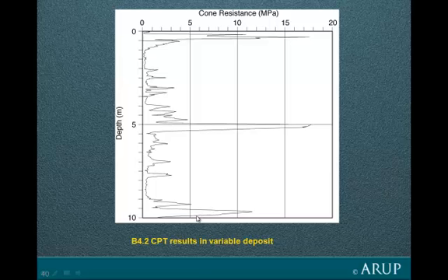Can I drive into it and be sure that it's then going to be the dominant stratum for the base? Or is it rather thin? Are we going to go back to some weaker material below? And this would affect the choice of characteristic strength for the base, and it might be very different from that for the shaft, which is taking an average.